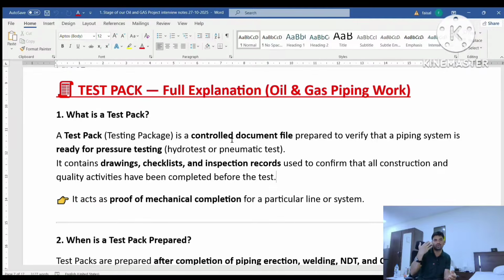Now you are going for the integrity testing. You have to fill the water inside and do the testing up to the test pressure. For the whole holding time, you want to check that the piping system is 100% leak free, with no leak anywhere.